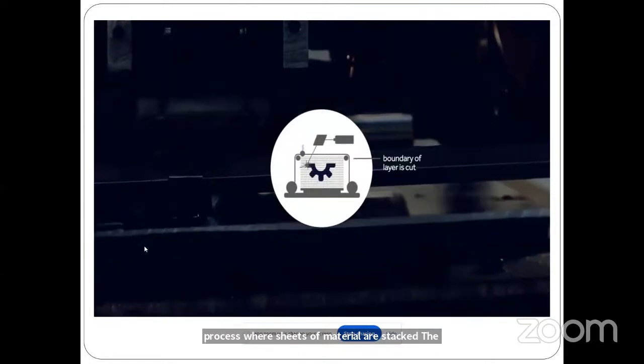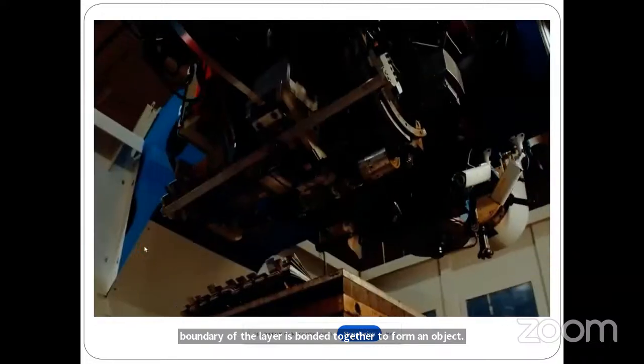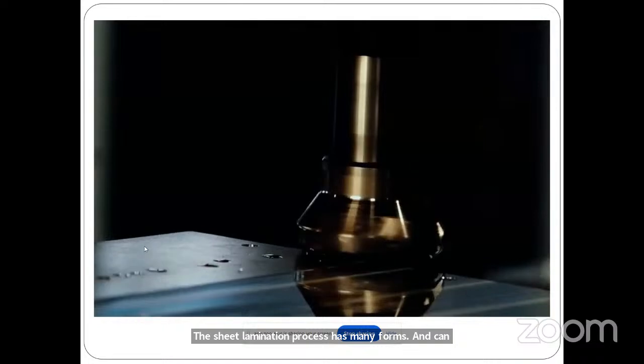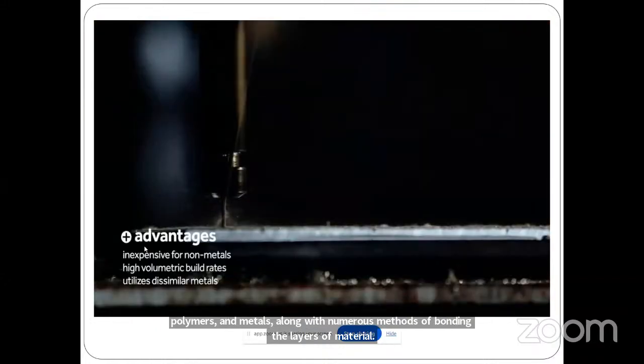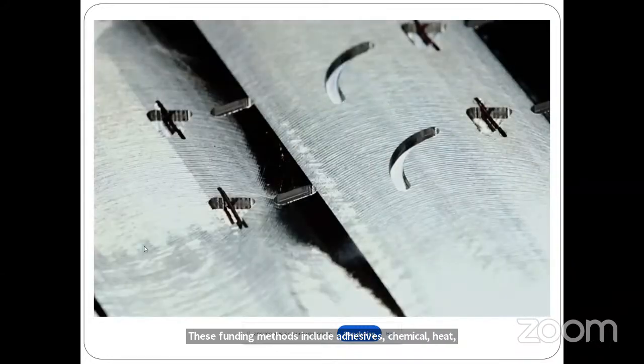The boundary of the layer is bonded together to form an object. The sheet lamination process has many forms and can utilize a wide variety of materials, such as paper, polymers, and metals, along with numerous methods of bonding the layers of material. These bonding methods include adhesives, chemical, heat, and solid-state welding processes, such as ultrasonic consolidation.